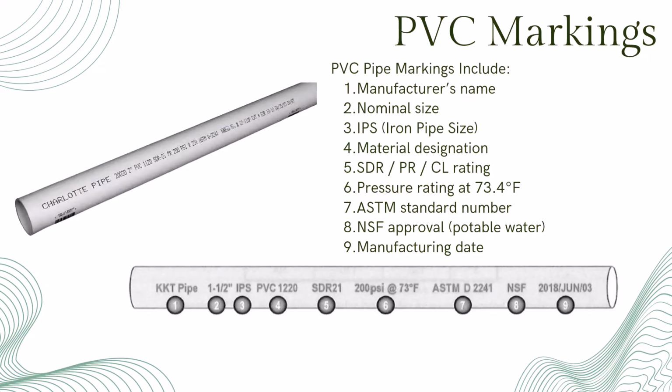Now about those markings. You've probably noticed writing printed along the side of PVC pipe every few feet. That's there for a reason. It tells you the manufacturer's name, the nominal pipe size, IPS (iron pipe size standard), the type of plastic material, SDR, PR, or class rating, the pressure rating for water at 73.4 Fahrenheit, the ASTM standard the pipe meets, NSF approval if it's safe for potable water, and the manufacturing date. Reading these markings is a quick way to confirm you're using the right pipe for the job.